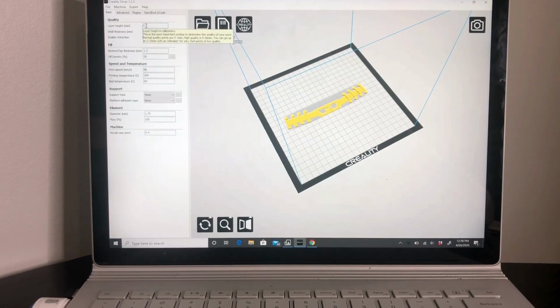So right now we have it set at 0.2 millimeters. So the extruder will go up in the Z-axis away from the bed in an increment of 0.2 millimeters per layer that it prints. As I'm sure you guys are familiar, if those of you that aren't, the printer will lay the material in layer by layer segments. And there'll be a video at the end of this lecture to show you guys that in real time and also a time lapse.